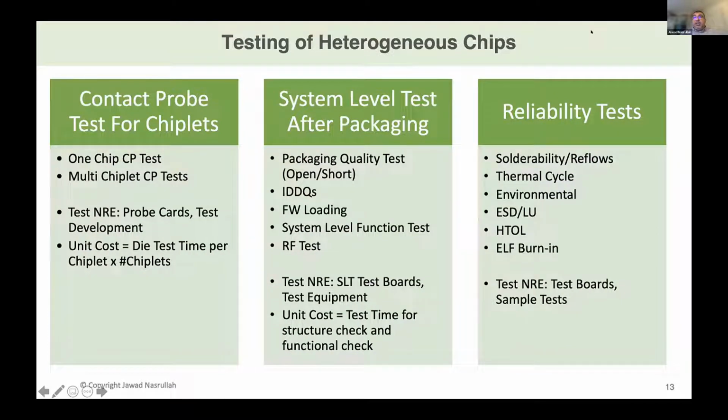So I'll just say a few things about what we learned in terms of the testing of these chips. So basically, we broke it into three different buckets. There was contact probe for chiplets and active interposers, and the probe cards and the testers that go into these fine pitch bump type of testing hardware, they're quite expensive, and that needs to be a consideration.